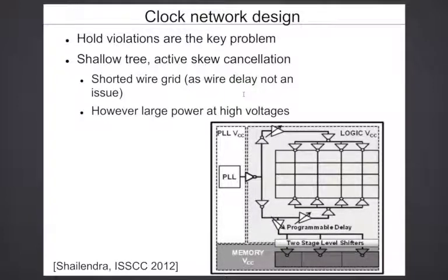The thing is, when you use subthreshold, what is the supply voltage to use? It's a little fuzzy concept, especially if you put in your feedback loop and have adaptive voltage scaling, etc. The supply voltage can be adjusted. So whenever you have a setup time violation, you increase the supply voltage a little bit and it will be okay again, right? Max timing will be taken care of. With all your feedback loop, you can easily take care of the max timing problem by adjusting the supply voltage.